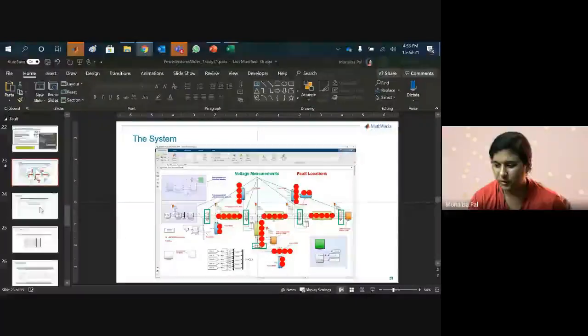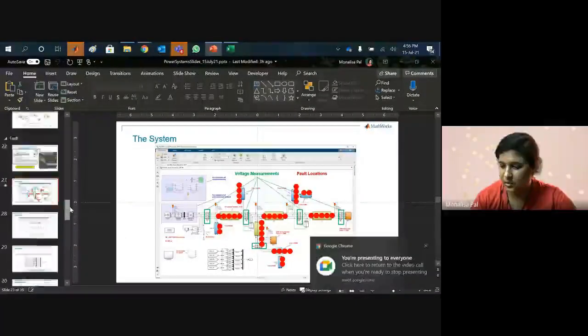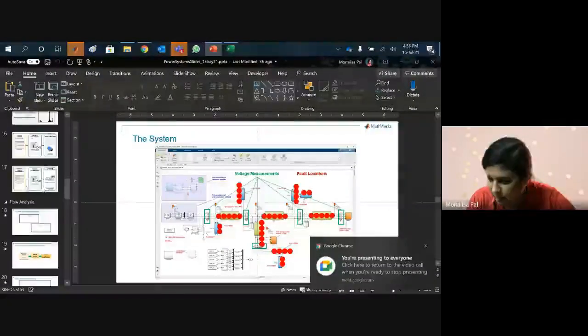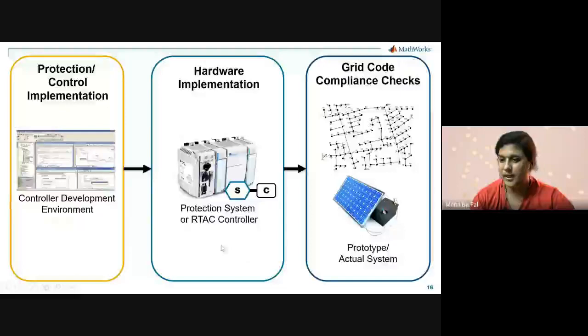So the workflow that we mentioned is generating C code first out of the Simulink model. Let me go back to that particular slide. Yeah. So the workflow that I mentioned was to have the model built in Simscape and MATLAB, then extract the C code out of the Simscape model and deploy that C code particularly in hardware.